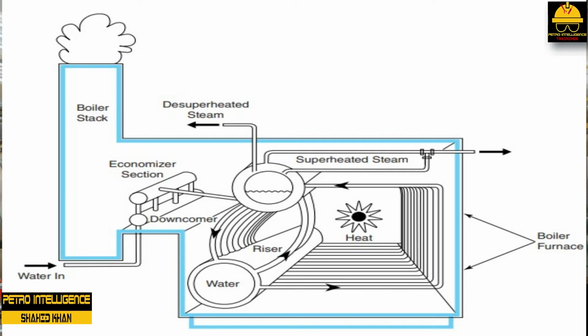Water circulation continues in a water tube boiler because steam bubbles in the lower drum move up the riser tubes and cause water density to decrease. The cooler water in the downcomer flows into the mud drum. The riser and steam generating tubes are physically located near the burners. Steam moves up the riser and steam generating tubes and into the upper steam generating drum.